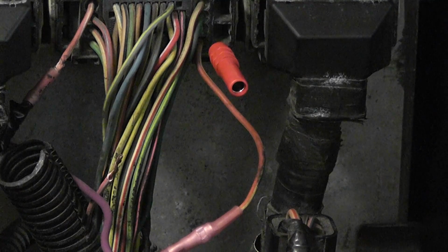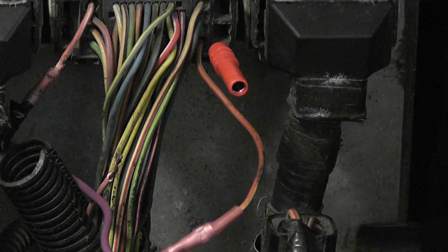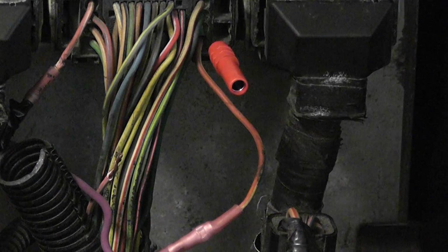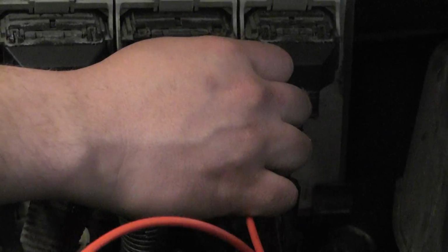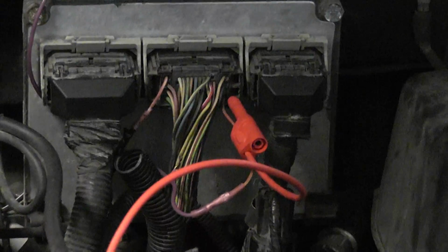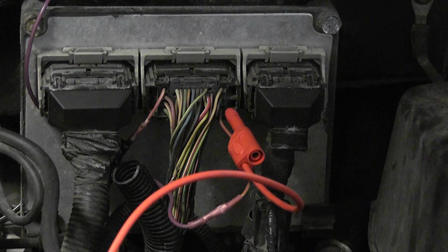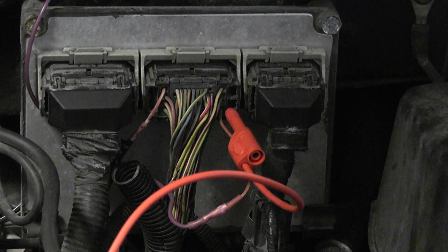Now, if you know how to do voltage measurements, how much time are we going to save here by just looking at a voltmeter reading and saying the harness is good? So that's what we're going to do. Kind of plug that back in. Our voltage measurement at this location is going to be key to our diagnosis. Again, if we see a steady 14 volts on this wire with the engine running, our harness is fine. And if we see a steady 14 volts and the harness is fine, why would you cut the wire and run a new wire? How much time are you going to spend wasting doing that procedure? Take a voltage measurement, see what you have.